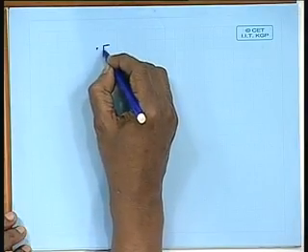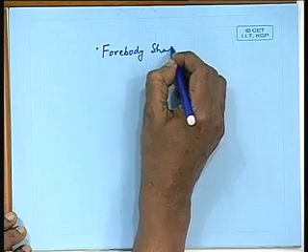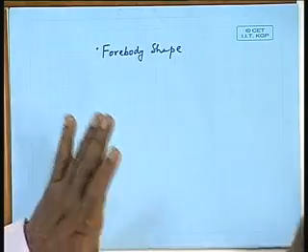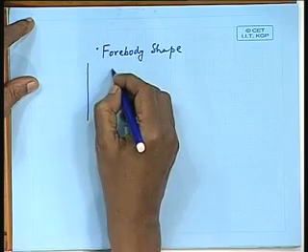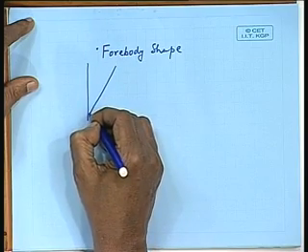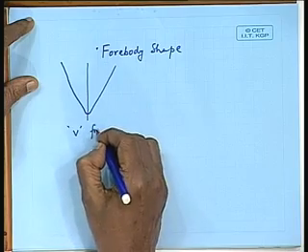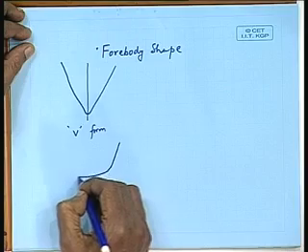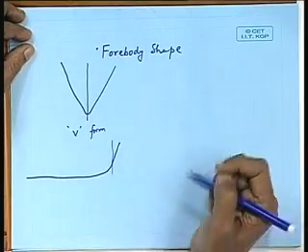Now, then next comes the fore body of the ship, fore body shape. We have 3 fore body shapes which are extreme, and we have to choose one of them or in between them. One is typically a fore body section shape, which is like this. This is called V form, like a V. Normal ships that have a shape like this will have a section like this.